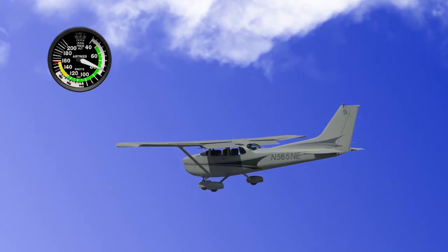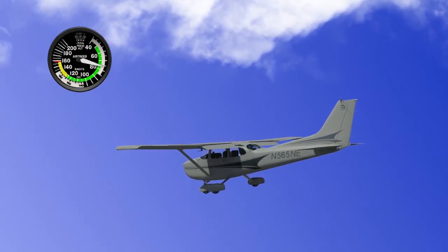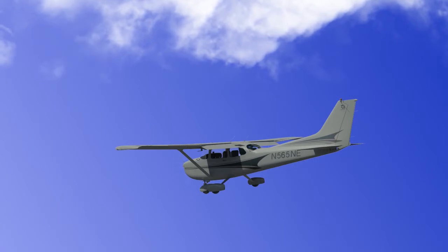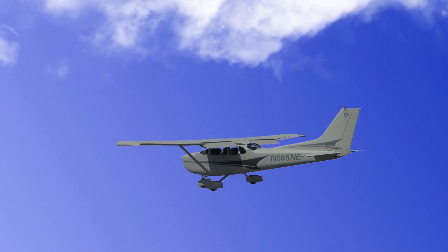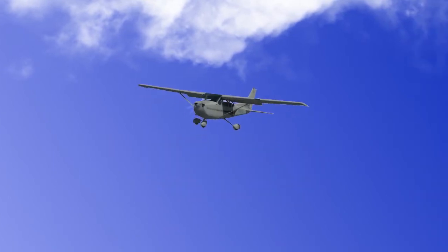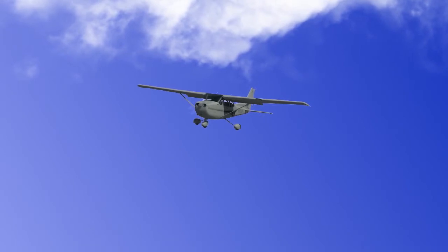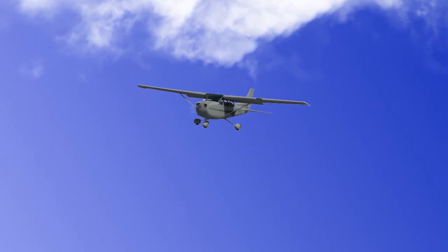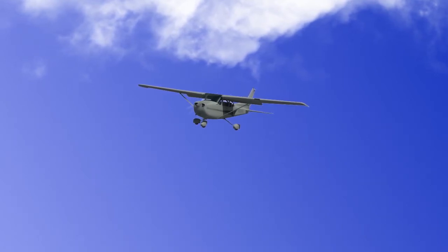Once approach speed is achieved, lower the nose and set the power and attitude until you are in a stabilized approach. Maintain this pitch until you reach your designated altitude. Smoothly start to pitch the nose up to maintain altitude. Your directional control will be maintained with the yoke and rudder inputs. Hold the airplane until you hear the stall warning horn.